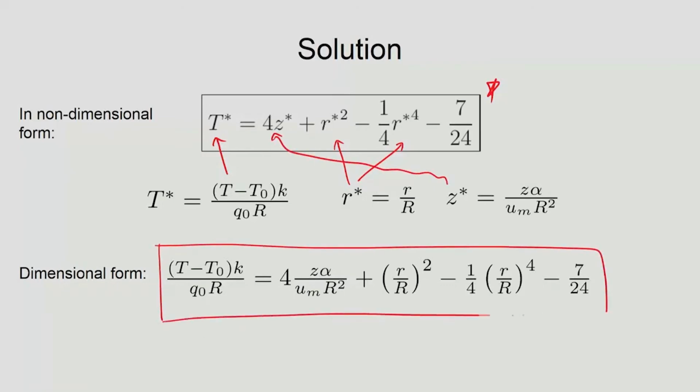Okay, so, in the dimensional form, now we have got the solution. Which means that T as a function of r comma z is now available. So, technically our problem is solved. We are done with the solution, and for the pipe at any r and z, we can then find out the temperature, subject to the boundary condition that the heat flux on the surface is constant, which is Q naught, that is also given here. Okay, so, now what we do is that we go ahead and use this solution to arrive at the concept of bulk temperature and Nusselt number.